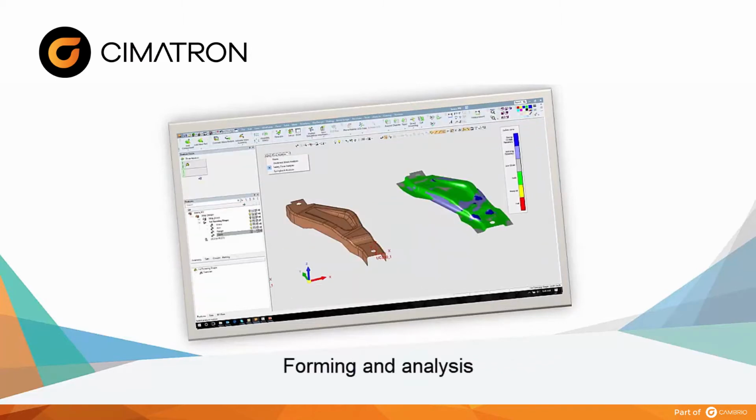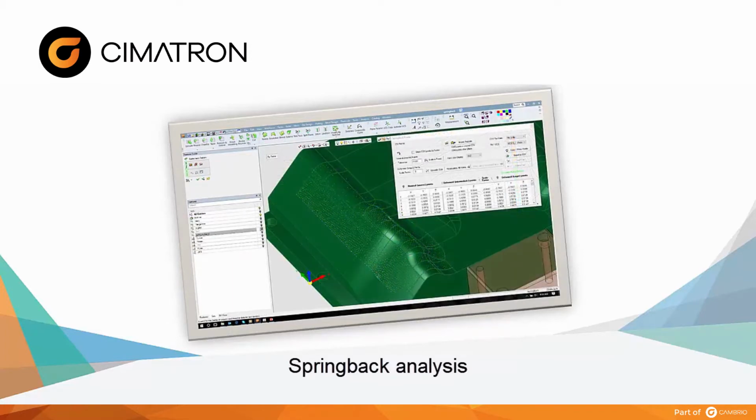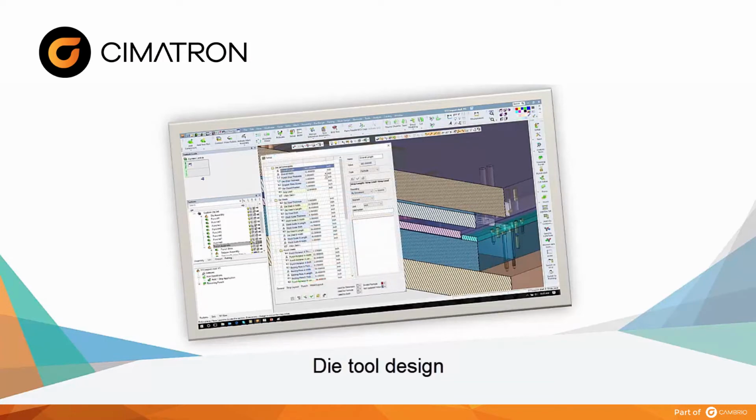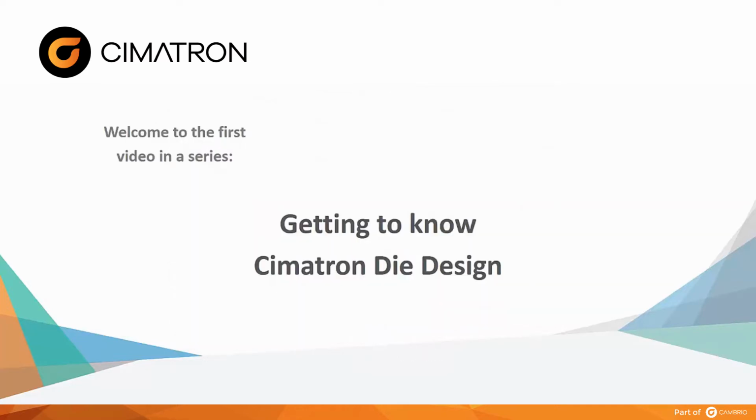We will consider what's involved in advanced forming conditions to analyze the part for wrinkling and tearing. We will also look at predictive springback and how that information then can be applied to deform the tool. And we're going to also feature Cimatron's powerful die design for creating custom die sets, factoring in punch clearances, working with catalog components, and also creating wire EDM punches, just to name a few.